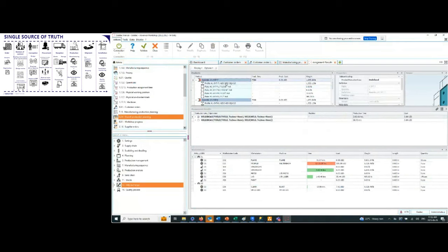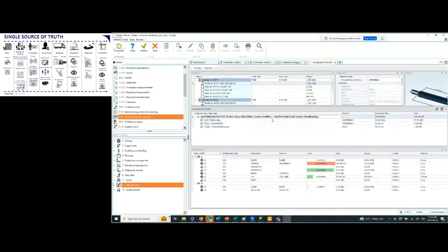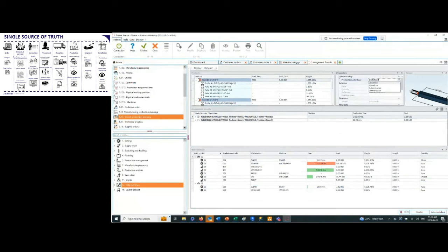Let's just be clear. But under this profile, I see that I only have one machine, which is the column back, that can actually execute the cut to length, holes that need to be applied, etc. Now, if ever I've hit critical mass and I need to execute by a set date, you can obviously choose to subcontract at this level as well. So here I can choose to disable the operation or subcontract it altogether. And you can be specific on which operation it is as well. Another point to note, if you wanted to just subcontract the entirety of the assembly, that is something that you can do here under properties.